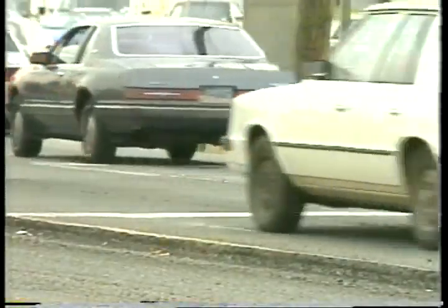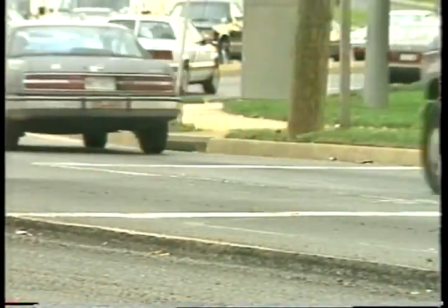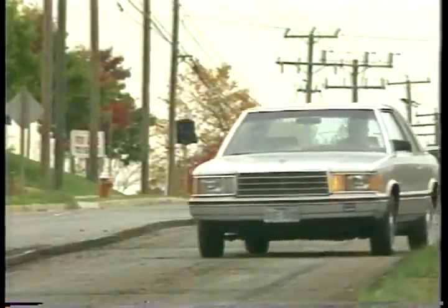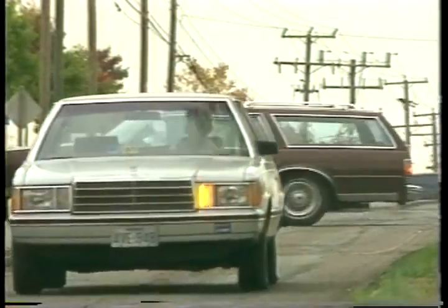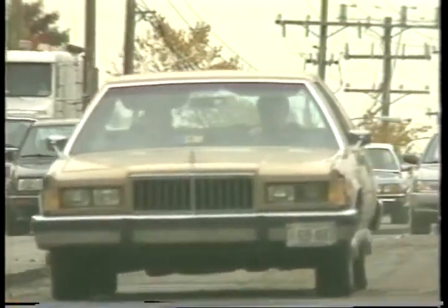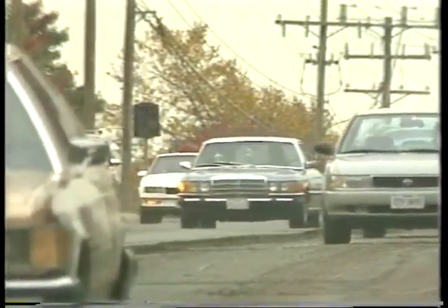Other questions to answer when considering how to handle drop-off are: how much traffic volume will there be? How far will the drop-off be from the traveled lane? How many days will the drop-off remain? And what will be the shape of the edge or slope of the drop-off? The plan may have to require paving or creating a wedge of gravel or other material to reduce the drop-off.